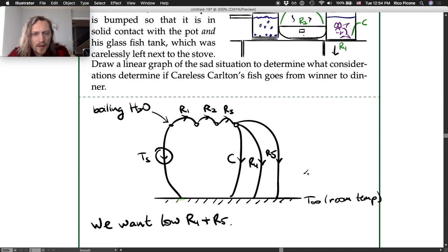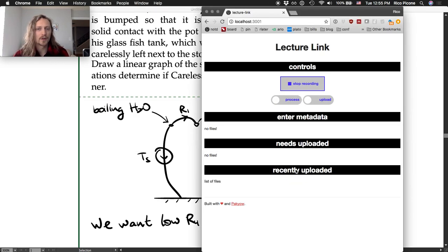But the first part is to be able to draw the linear graph. Once the linear graph is drawn, it's the same process that we learned in volume 1 of the system dynamics, so for electronic systems and mechanical systems. So now same applies. We have source, D types, A type, and we can draw a normal tree and derive the state equations.